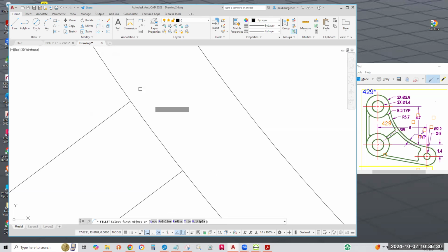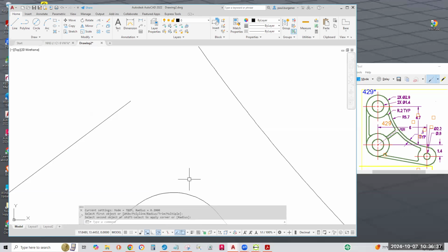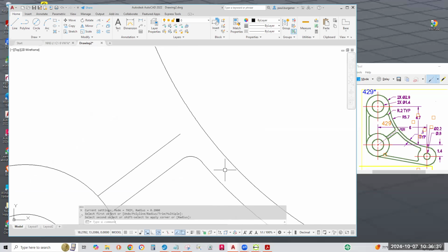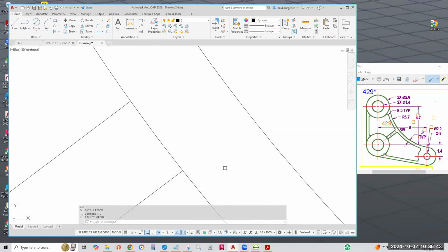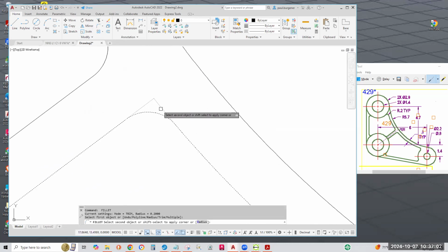Let's go to fillet. Fillet, we already set the 0.2, so let's click, and it truncated. Did I forget to trim that? All right, trim. Well, with the same flyout as extend, enter, erase it. Enter to finish, trim, click. Okay, seems to be working now.